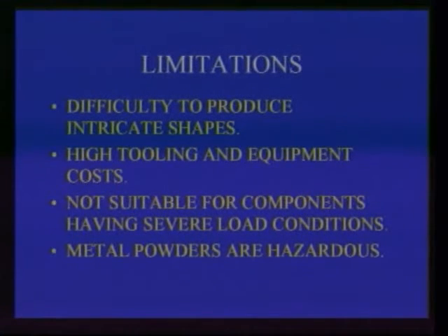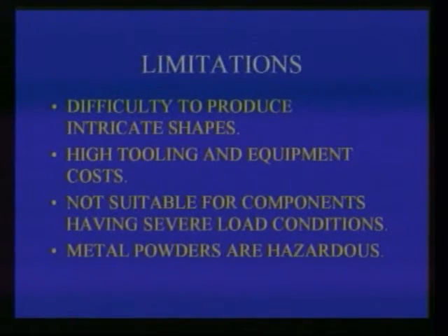The third limitation is that it is not suitable for components having severe load conditions. These powder metallurgy components are only suitable for moderate load applications, because these products manufactured by the powder metallurgy technique have less strength. The last limitation is that the metal powders are hazardous.